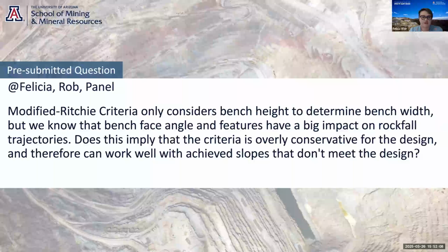So it's not just berm widths, but you're also considering bench heights and batter face angles in one go. The Ritchie formula is conservative, but it gives you a good rule of thumb that you can apply, for example, in a feasibility study, or pre-feas, when you don't necessarily have a lot of experience in that particular geology.